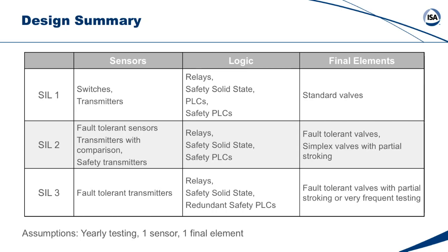Logic solvers, you can rule out any kind of general purpose PLC, and you're not even going to be allowed to use a safety configured general purpose PLC. Everyone would use third-party certified for use in SIL 3 safety PLCs, which are much different than general-purpose devices in that they have much higher levels of diagnostics. But hey, there are relays. There are solid-state devices that actually meet SIL 4 and SIL 3 as well.